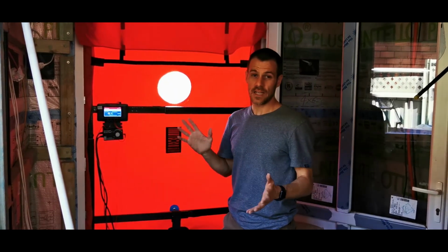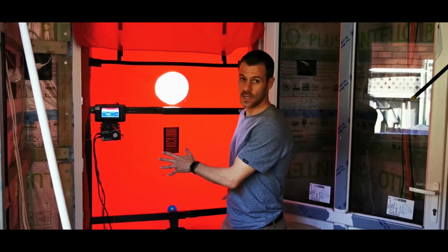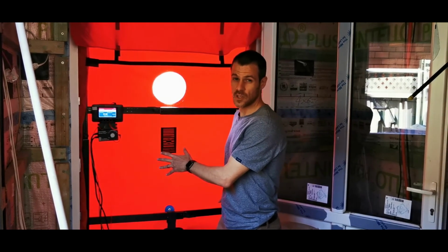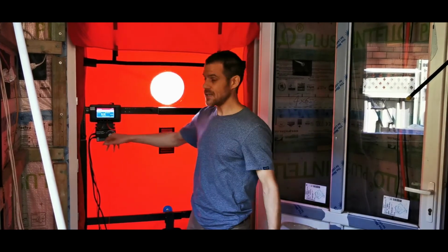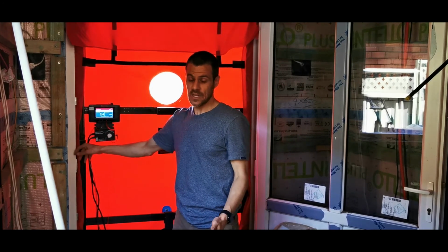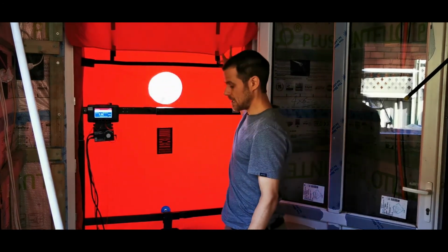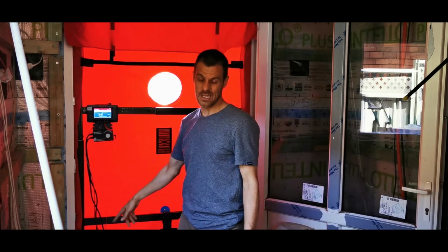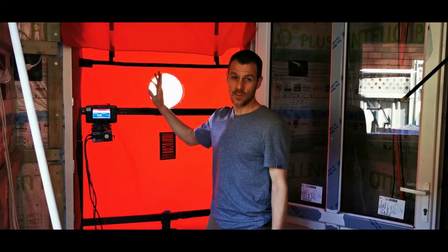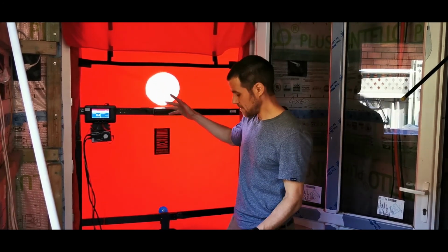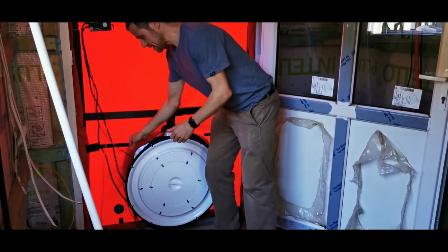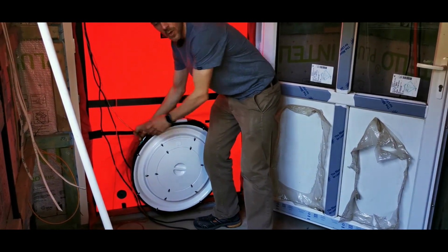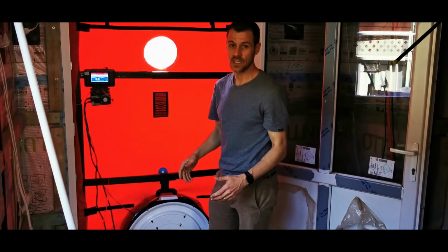People often ask, is doing the blower door going to contribute to leakage that wouldn't normally be there? Can you seal around this during the blower door test? Yes, you can. You can seal around this with some extra tape, gaffer tape or something, to make this seal better during a blower door test. They also ask, is leakage like this, where you pass a hose or a power cord through, going to contribute to the leakage?